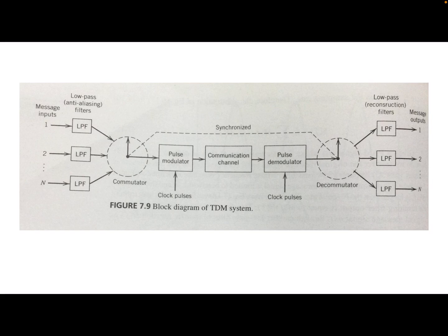In this way, some of the time interval between adjacent samples is cleared for use by other independent message sources on a time shared basis. We obtain a time division multiplexing system, which enables the joint utilization of a common communication channel by a plurality of independent message sources without mutual interference among them.